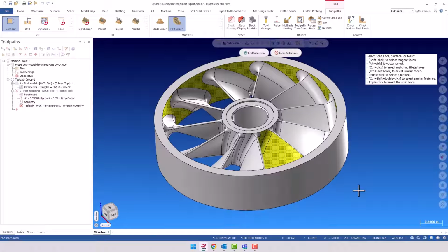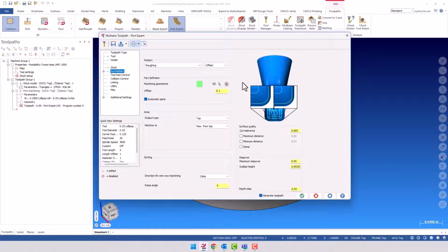Again, we don't have to go create extra geometry. If I say in my selection here, it's going to automatically create the spline. If you were doing this with, say, a unified toolpath, you would have to create your upper and lower guide curves. Then you would have to draw a spline that defines the middle of that shape. And then you would have to make those selections to get your toolpath control, doing it that way. Just as an example, I don't have to do any of that.